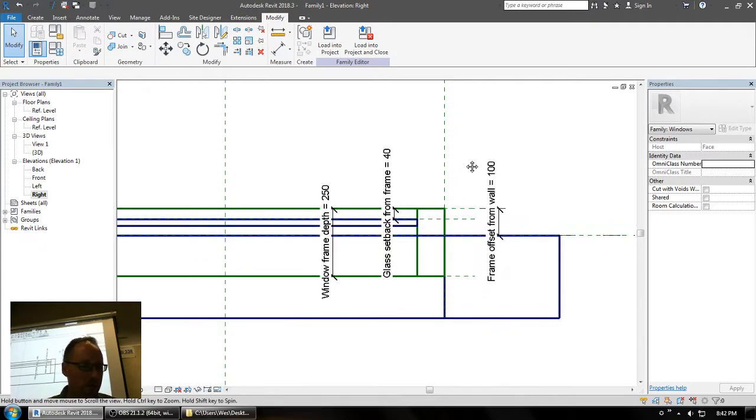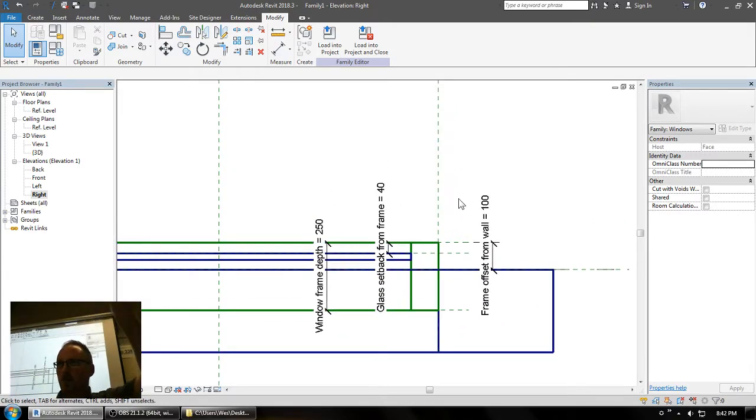Okay, what we're going to build is a little hinged part of our window. So if you folks are getting into renderings and you'd like to make, say, the vent frame on your window, whether it's an awning type window or a casement window, you'd like to show the operable part of your window hinged outwards for the rendering. So it kind of gives your building that lived-in look. You can use this process to make that happen. And we're going to do it here using reference lines instead of reference planes.